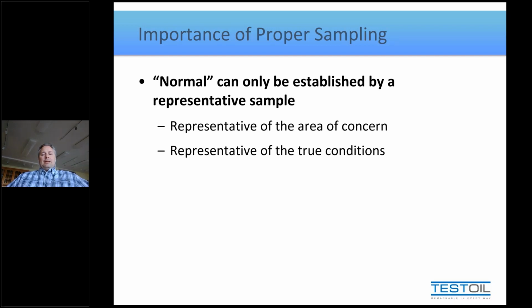The problem with the word representative is it's hard to define the term representative without using the word within the definition. And generally when we mean representative, we actually have 2 sides to that definition. First and foremost, it's representative as in it's showing you what you want to see. Right? If you're concerned about the contamination levels in your sample or in your machine, would you take a sample before or after a filter? Well, obviously you would think we should take it before the filter because the filter will remove the contaminants and we wouldn't see them if we sampled it after the filter.